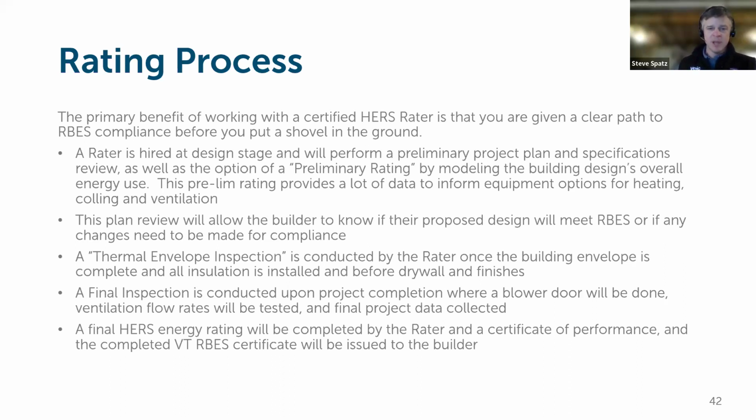So that final inspection occurs, the data is collected, and then the HERS rater takes those final building data points, puts them into the energy model, into the rating tool, and completes a final HERS rating and a HERS score. And that rating certificate accompanies the completed RBES certificate as the project documentation for showing code compliance.